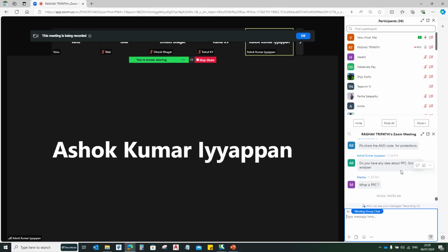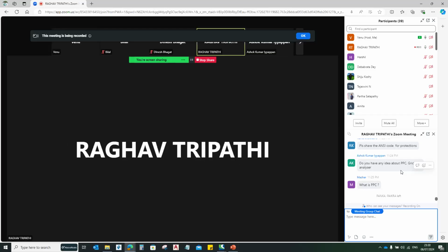For example, one user may generate power with some quality, and another user may generate with some other quality. Without checking these power qualities, if you impose them directly onto National Grid, that will have a big impact on the National Grid interconnected system.